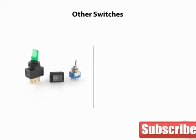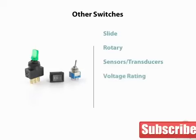Other switches include slide switches and rotary switches. Switches are even used as sensors when their actuator is connected to a sensing device such as a cam for positioning sensing or a diaphragm for a pressure switch. In selecting switches, always observe the switch's maximum voltage and current rating, and stay well below it to make sure the switch is not electrically overloaded.